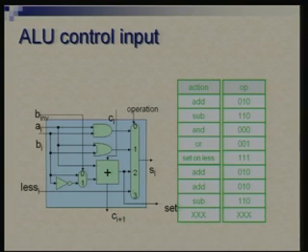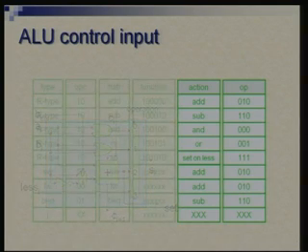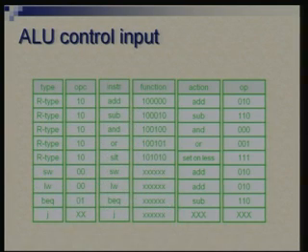So, based on the way we have designed the ALU, we can define what control input is required for each case, and with this our picture is complete, and here we have the complete table. So, this is the truth table for the second controller, or the ALU controller, where we have an 8-bit input and a 3-bit output. So, one stage of the design finishes here.